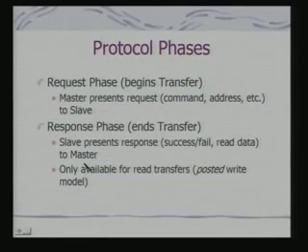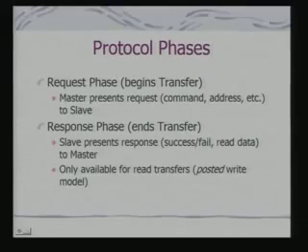There are protocol phases in this standard. If you look into it, you will find a very similar kind of protocol, but structured in a slightly different way. You have a request phase which begins the transfer, where the master presents request, command, address, etc. There are more elaborate definitions, I am not going into it, I am just giving the basic idea.